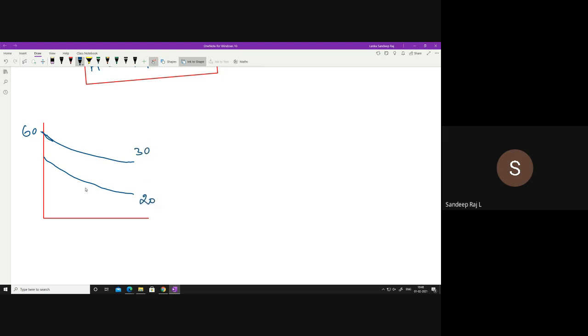Here from 20 to 26 it's moving. Even now it should make sense. 30 is greater than 20, 60 is greater than 26. So all these temperatures should make sense for you here. You can see that they are moving counter to each other. So if I have to write the delta T1 on the left here, what are the values? Delta T1 is 60 minus 26.